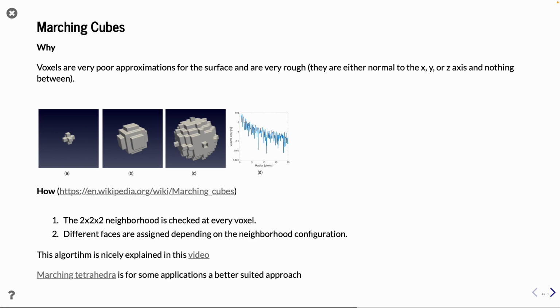That is what is done using Marching Cubes. It's mostly done in 3D, using a 2x2x2 neighborhood. That gives us a lookup table that tells us which kind of triangle we should use to identify this area. And the refined version of Marching Cubes is that you actually look at the points and try to find exactly where you should put the triangle within it.